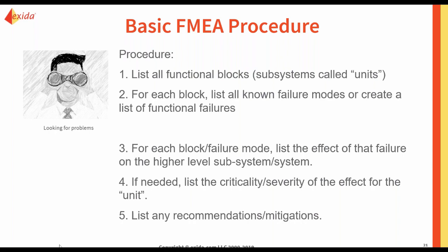But I can tell you that we've looked at many, many FMEAs in the past. And we've discovered some pretty poor work. What goes wrong? What do people do wrong? Well, they don't have a good list of failure modes. So you might ask, where do I find a good list of failure modes anyway? And if you don't have a good list, you're going to miss some of the failure modes. And I have to say that's probably the number one thing that I find.